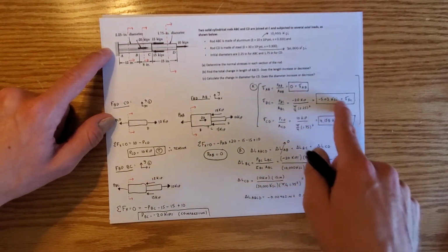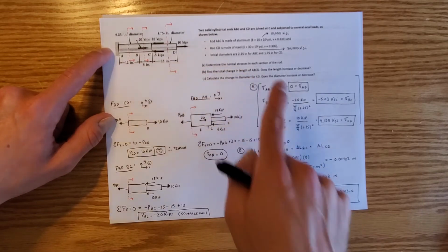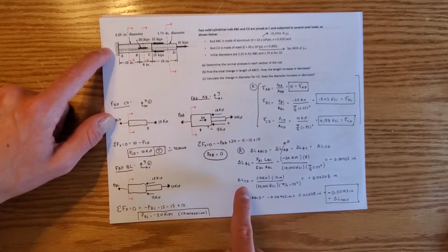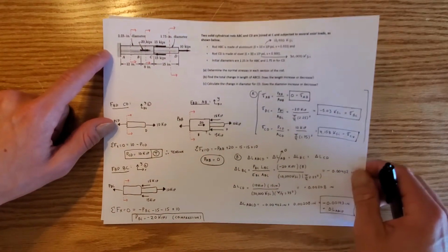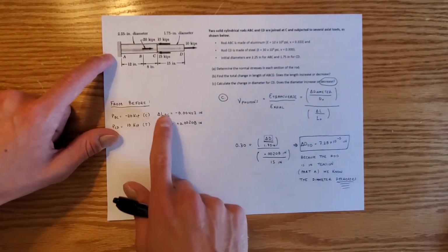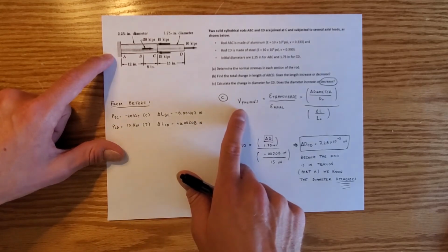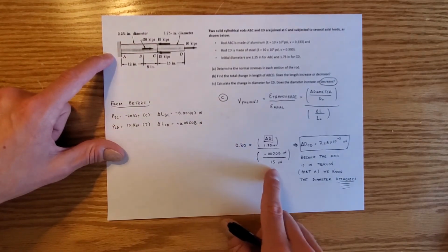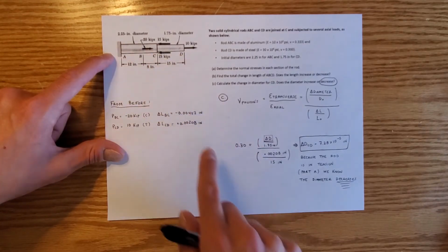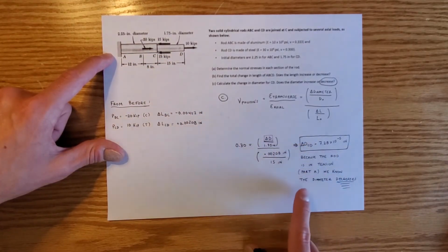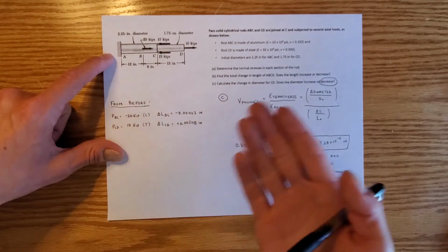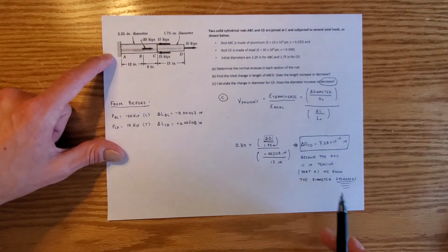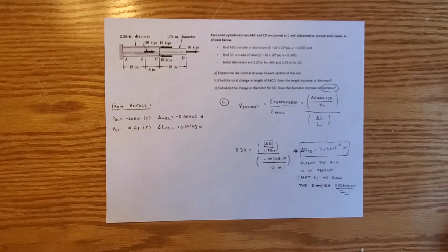Then we solved for the normal stress in each section of the rod, which is what we were asked for in part A. We then did a change of length of everything using the rearranged formula of Young's modulus for change in length. We then added those values together and found the change in length of the total rod. And last but not least, we used the change in lengths from the previous section and our knowledge of Poisson's ratio to find the change in diameter of one of the sections, which was section CD. Because this is a rod that is in tension, which we know from part A and B, the diameter will decrease. And that is how you do an internal loads problem.